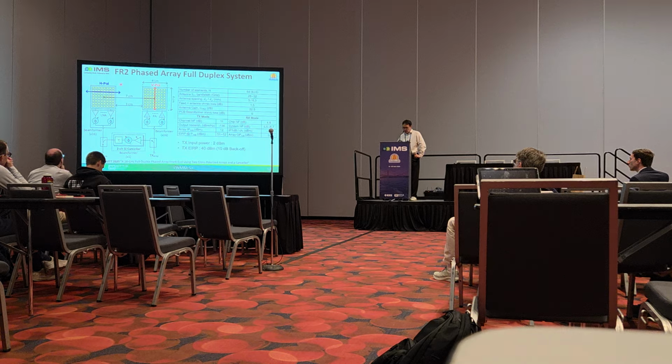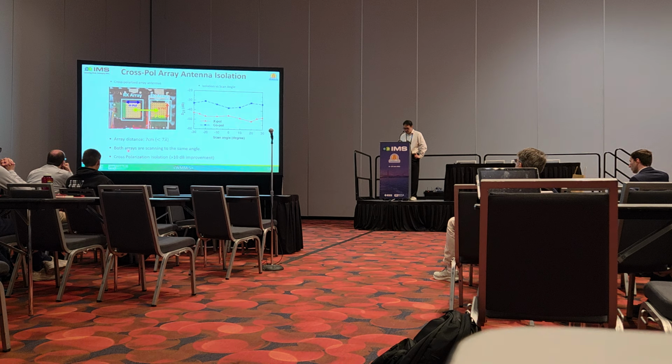And this phased array system has a single RF canceller. Actually, for this canceller, we use the beamformer. Every 4 antennas have a single beamformer. That beamformer is also used for the canceller. We only use 2 channels for 2-channel self-interference cancellation.